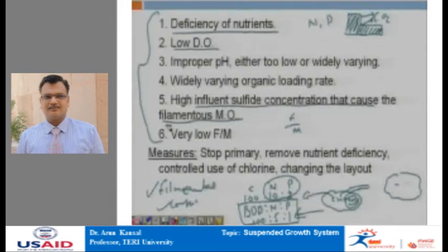because at times the plant operator may not have prior knowledge of when the wastewater is getting excessively diluted in terms of nitrogen and phosphorus. There is a prolonged power supply failure which is beyond his control, and variation in the incoming wastewater. These are some of the things which are beyond the plant operator, and that is why sludge bulking is a problem which is encountered by almost all wastewater treatment plants once in a while. So it keeps on happening, no big deal about it.